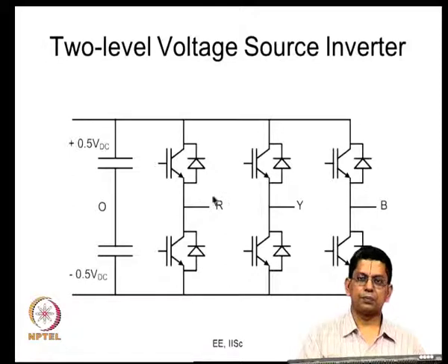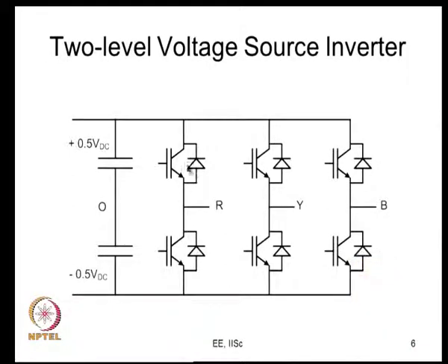So, this is the 3-phase inverter. Every leg is a pair of complementary switches. One turns on and turns off, the other turns on, and vice versa. But every time there is a turn on and turn off, what happens? Initially there is this voltage, when let us say this is conducting, so the entire voltage is being blocked by this. When this device is to be turned on, there is voltage across it, and the voltage has to collapse down to 0, and the current has to rise through this particular device. The current starts rising well before the voltage starts falling, and therefore there is a certain amount of loss here, which is what we are going to look at today.